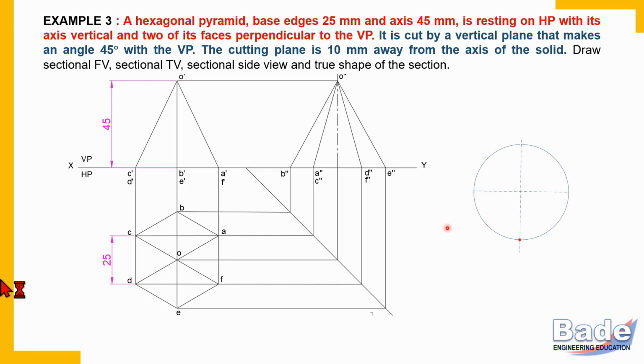Now same radius in compass and from ends of vertical diameter. Now listen, this is very important. If you want hexagon with two of its edges vertical, then consider ends of vertical diameter.